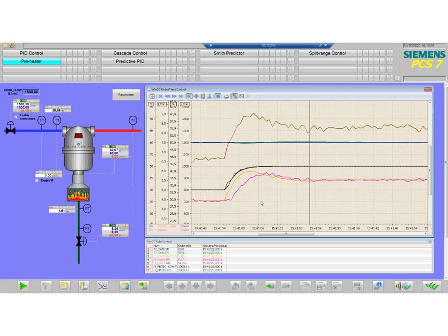If we look at the curves and the responses with the feed forward again, you can clearly see here in orange that the output of the controller is clearly following the product flow increase, right? In this feed forward, we have used this K loss and we have used it too small. So what the feed forward has done is ask for an increase in fuel flow that is a bit too large, and you can see that the controller has to correct for that.